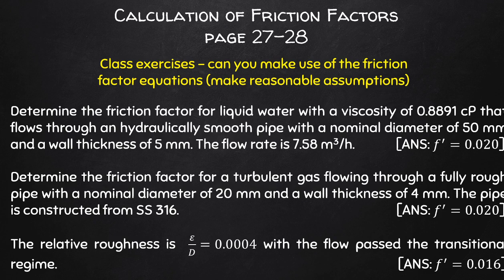And this is very useful because oftentimes in our initial calculations, we aren't able to determine a friction factor yet. And so we kind of have to guess first and then do a recalculation once we have some values to calculate f prime. Fortunately, f prime does converge quite quickly, so we only have to do 1 or 2 iterations at a time.